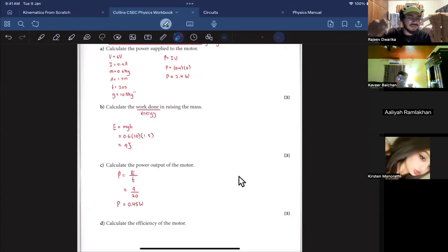So let me ask you a question. If I was to ask you how much of the power is being wasted, what would you tell me? How much power is being wasted? 1.95. Yeah, 1.95, because we actually need 0.45. Why are we supplying 2.4 watts? So that brings me on to the last thing: calculate the efficiency of the motor.